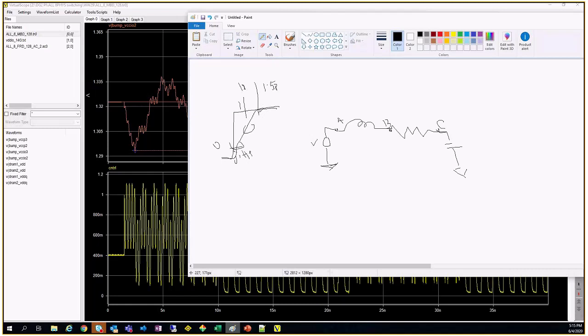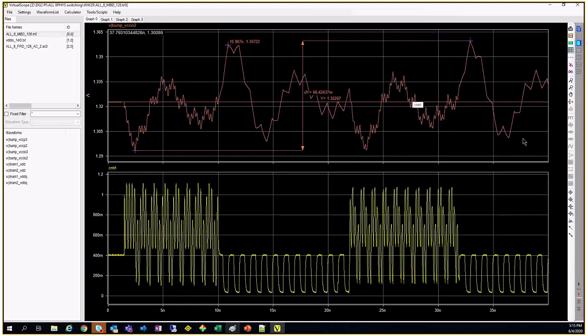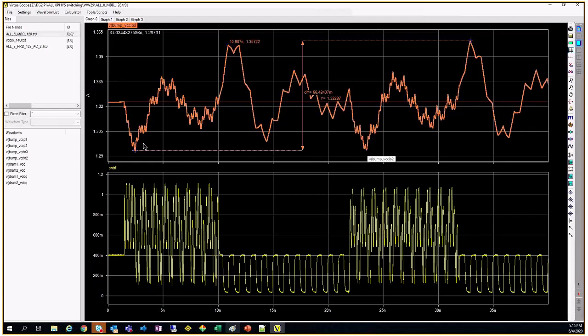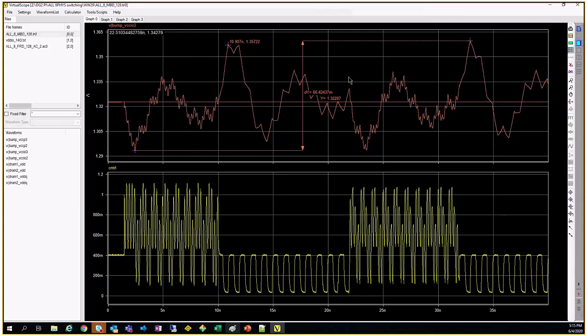More than that, it will skip it. If you sample at 1.5, it will miss it, right? So that jitter is modeled in, and by that, in reverse, they calculate using some formula and find out what is the peak to peak noise for which you can get an acceptable jitter. So this is why they call it noise. This term you will hear. So this peak to peak is very important.